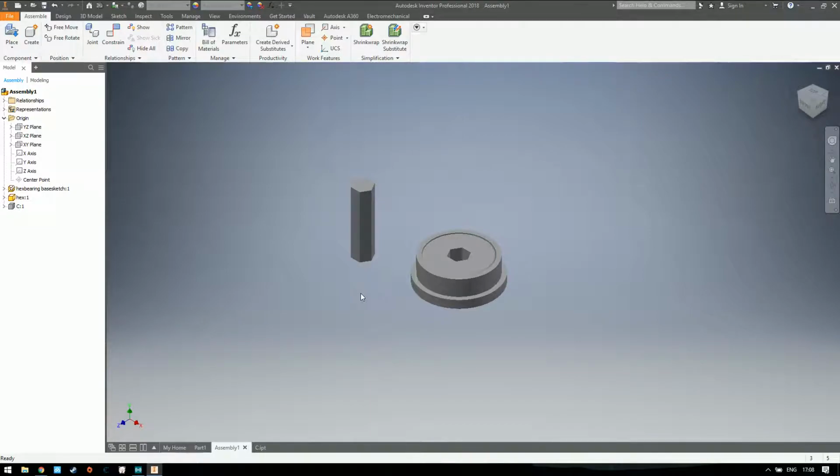So I still highly suggest you constrain each plane with the origin when you are doing something pretty important, for example, building the entire file for the shooter, creating a gigantic assembly file. Then you probably do that. But if you're just putting an axis inside the wheel, I'd say just ground it. It's really quick and helpful.